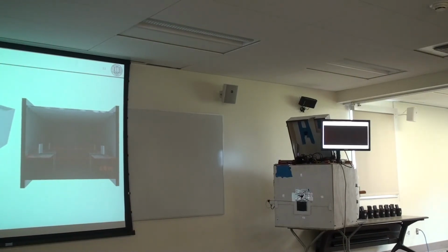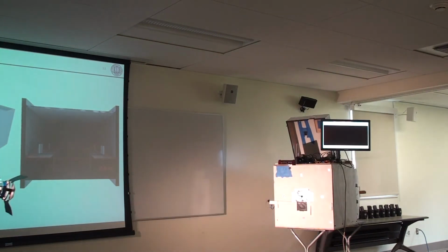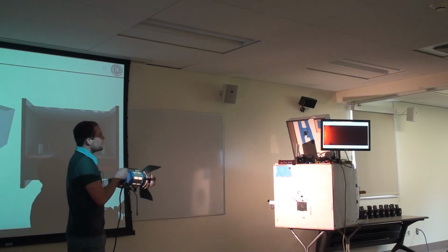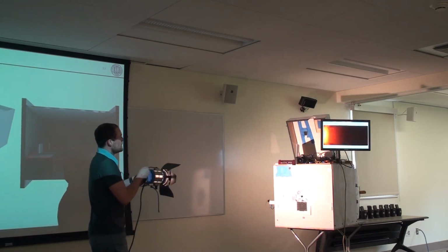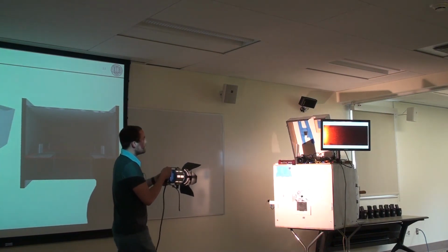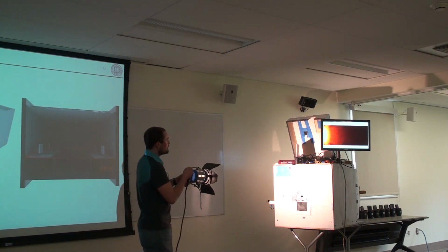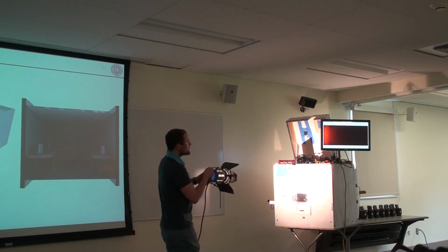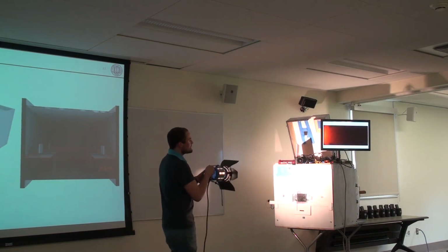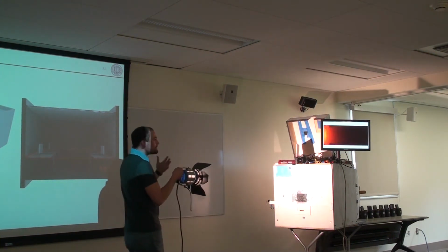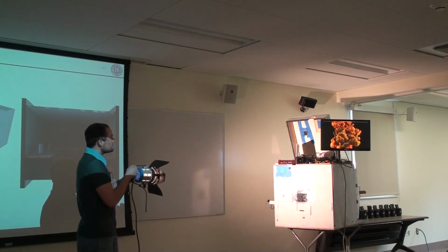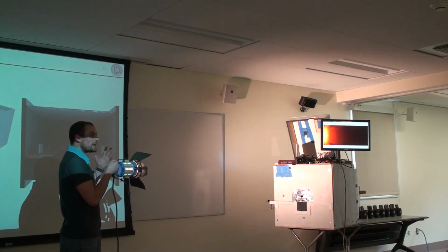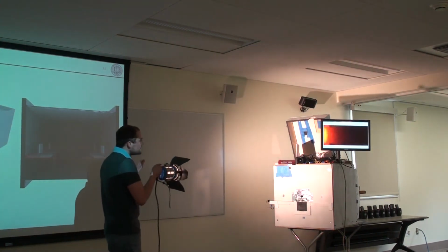So the floor plan looks very, very dark. But as we move up, you can see it's starting to get lighter and lighter. Eventually, we're going to overcome the threshold of the control law, and our window's going to shut. So you can see now the light's a lot less. You can imagine maybe there's a big cloud coming over, and so the light's a little bit less, and the controller now says, well, it's not as bright, so we can open the windows back up, right? And maybe it comes back.